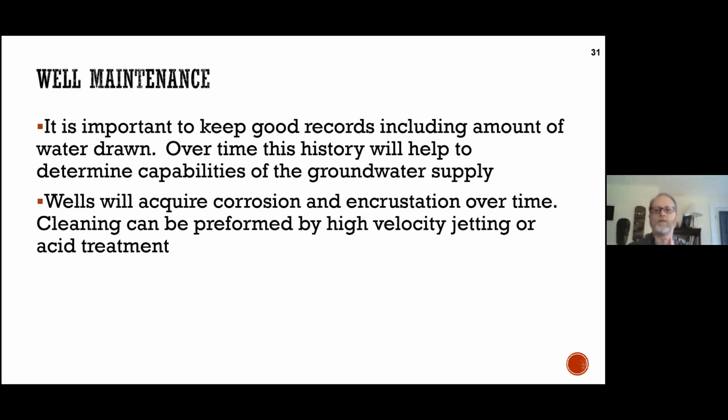It's no different than working in a pump station or a pressure regulating chamber and maintaining records of what's the upstream and downstream pressure, when was the last time that the globe valve was taken apart and serviced, or the diaphragm replaced, what's the maintenance cycle on the pilot valves and the associated plumbing. Wells are exactly the same.